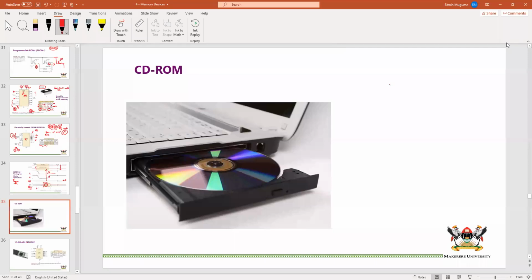And then let me try to draw a CD-ROM. When you are writing, you use a laser on each spot. If you were to blow up the disk, there are going to be certain spots, maybe a certain distance apart from each other. For each of these spots, you are going to make it either a 0 or a 1. You make it a 1 by digging a little pit. By digging, I mean you use a high-powered laser that burns that area and creates a small pit. A pit is like a small depression. And so here I've stored a 1.